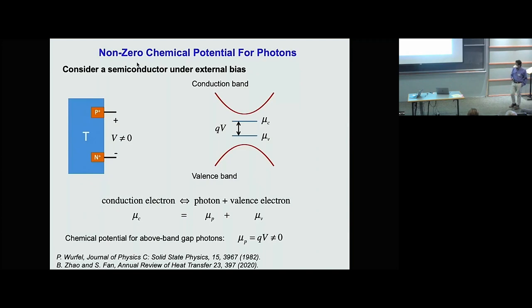So in this case, the electron and the hole can radiatively recombine inside the intrinsic region, with a chemical reaction-like equation as indicated here, where you have an electron jump from conduction band to valence band to emit a photon. So the point here is that every transition produces one photon. So there is a relation between the number of electron-hole pairs and the number of photons produced.